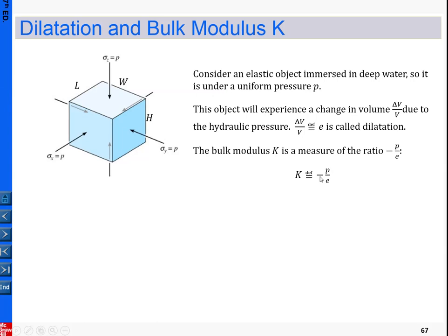And here why we add a minus sign, because you can imagine the whole volume change becomes smaller, so in reality E will be negative. Okay, so basically the whole quantity P over E in nature is negative, so we artificially assign a negative sign here to make the whole quantity positive, as defined as the bulk modulus. So again, here we involve the calculations of two quantities, and in particular this one.